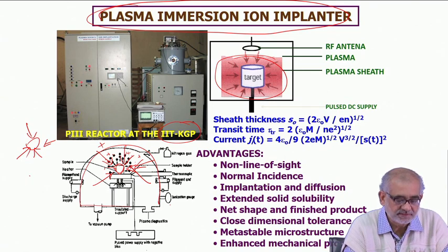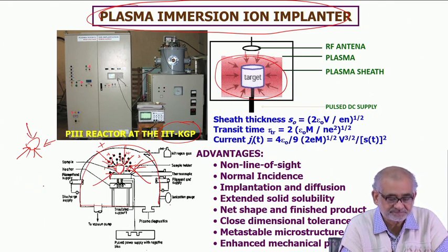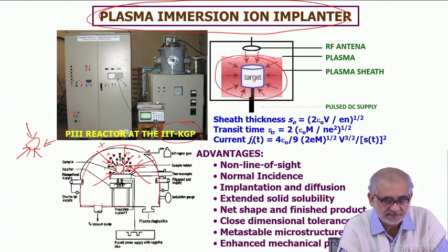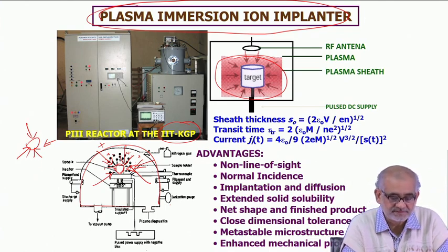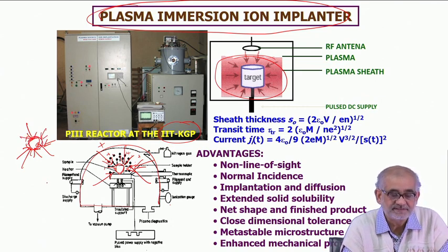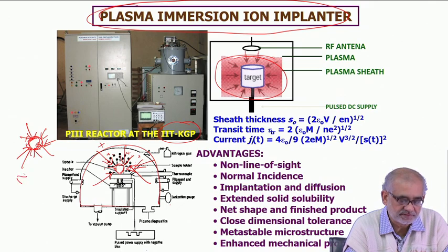And normally in gas nitriding or plasma nitriding, you have the sample exposed to the atmosphere and then a particular environment, and the atoms or the ions flow in and sit onto the surface, and here you are projecting them, propelling them onto the surface. So the implantation is very uniform, and that's why it's called a typical